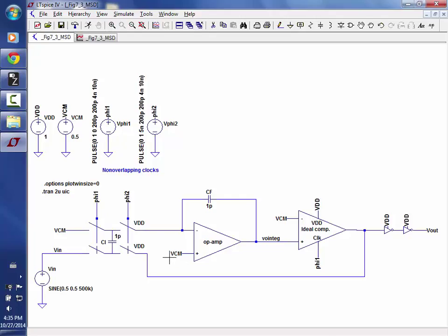Yeah, the comparator. If I reduce the signal swing here, the comparator gain, its digital output, 0 or 1, divided by the swing here, jumps. If I reduce the signal swing, the comparator gain jumps. So it keeps the forward loop gain equal to 1. Is everybody clear on that?